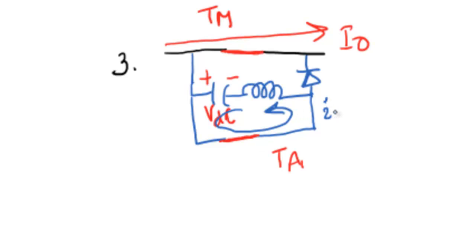Understand, this is IC. So slowly this capacitor energy is transferring to the inductor, the voltage across the capacitor will be reduced, and the current flowing through the inductor will be increased. So that's what is happening here. At one point of time, all the energy will be transferred to the inductor.